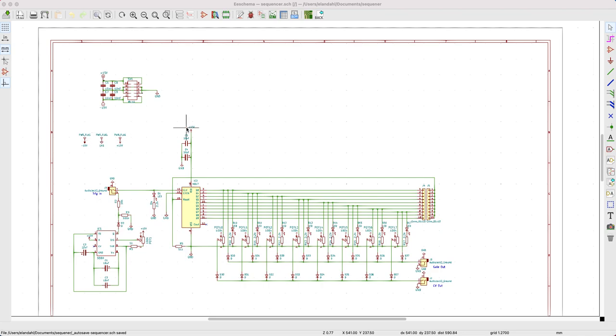For instance, over here where the voltage comes in that powers the 4017 decade counter, that is simply labeled, and it's understood that it connects through these power supplies. I don't have to actually draw a wire to them. This makes the diagram a lot easier to look at. You can continue with this idea and break up schematics into multiple pieces where you have labels not just for power but for different signals as well.